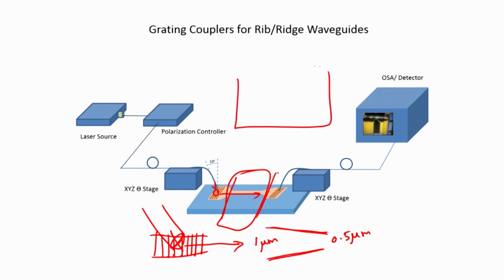If you want to measure a loss of the waveguide, for example, we can consider fabricating different lengths of the waveguide on the same substrate, and say for example from here to here is one, I will make another smaller waveguide, and the loss differences can be measured. For example, this is an extra length, L and L dash. So, the propagation loss for the extra length will be estimated by measuring the output optical power.